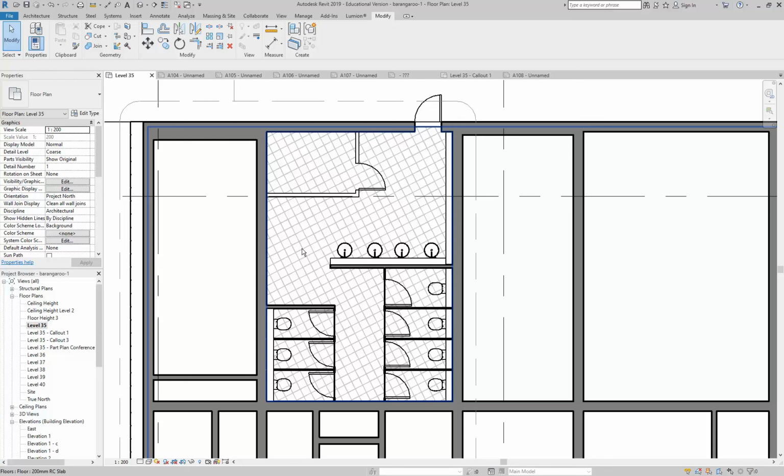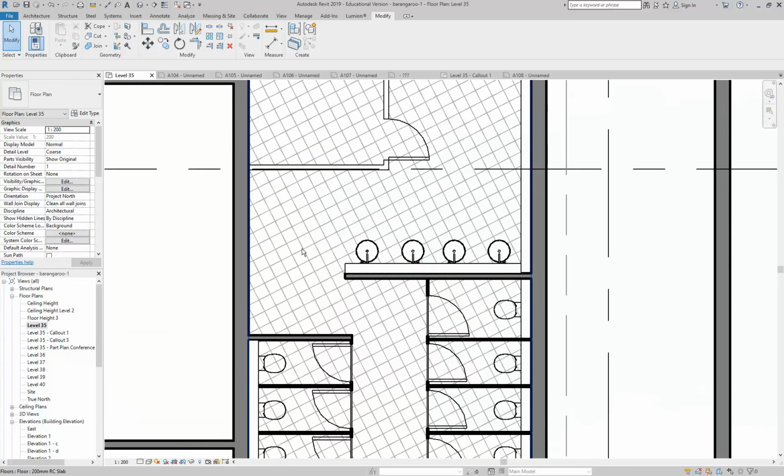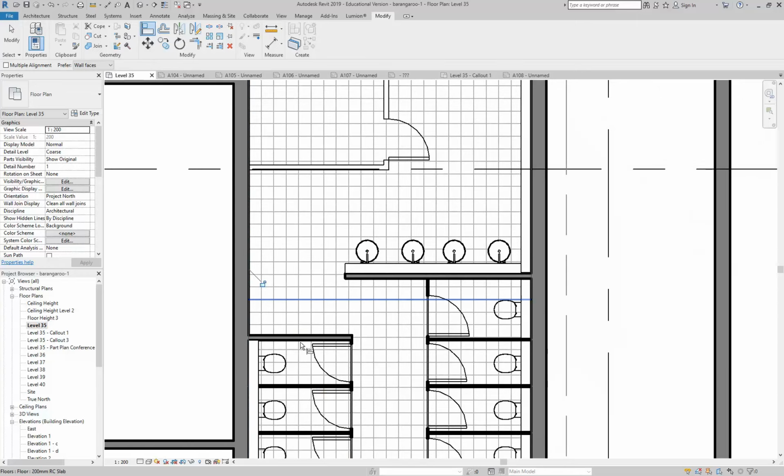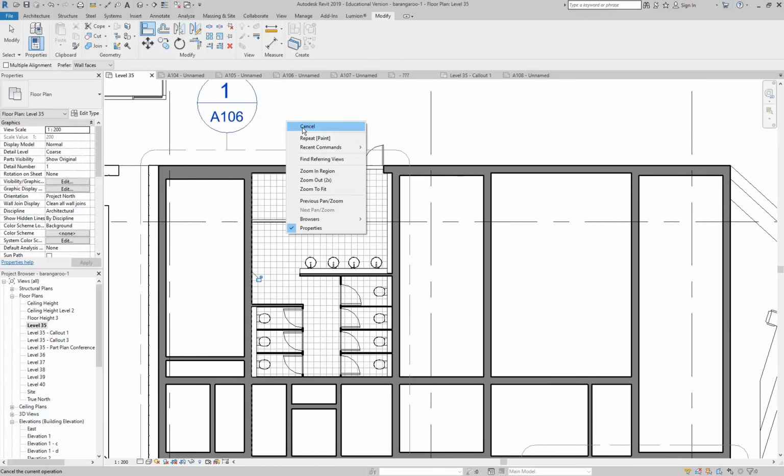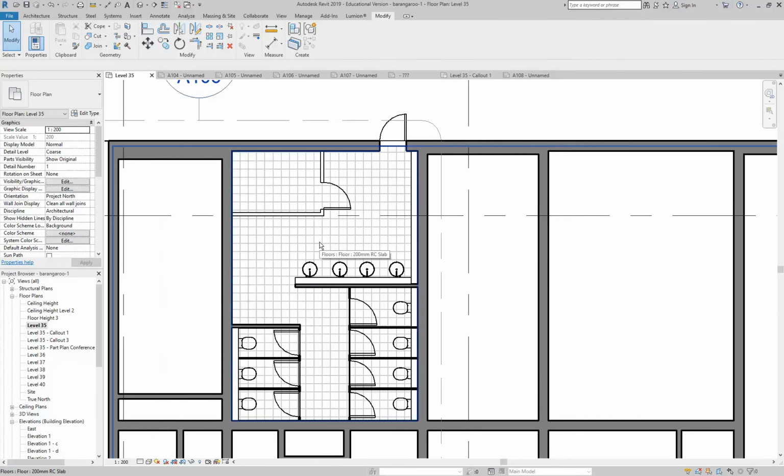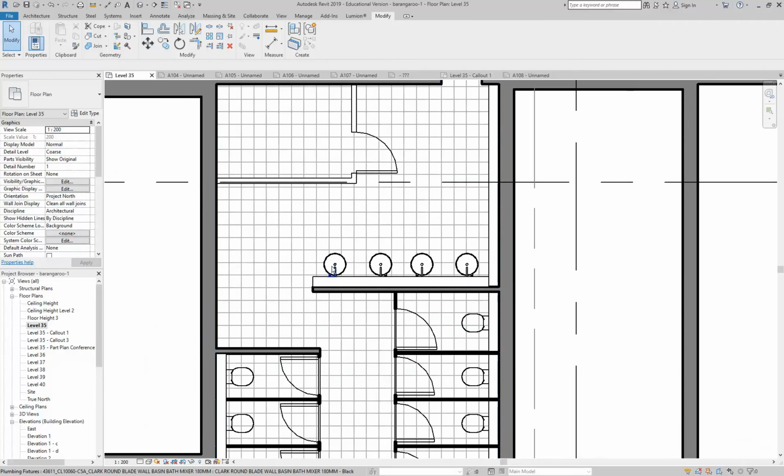So the issue there is just the alignment of the tiles, and it's picked up the orientation of the project, which you'll see behind the scenes still has that as the project north, because the building's been rotated, but not the project. So it's easy to fix on the fly. If you go to use the align tool, you can pick a wall, and then pick one of the edges of those tiles, and it will line up, no problem. So that's fine. Yeah, that's right. And it's nice. It does go on to lots of things.